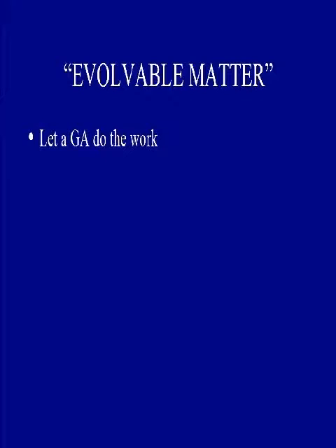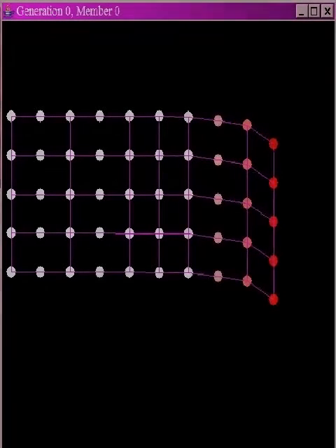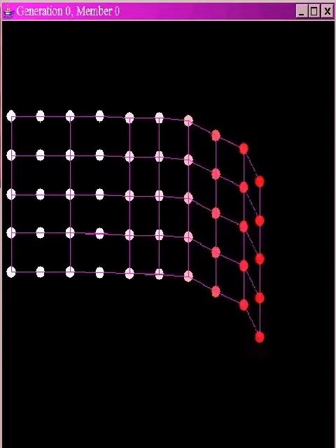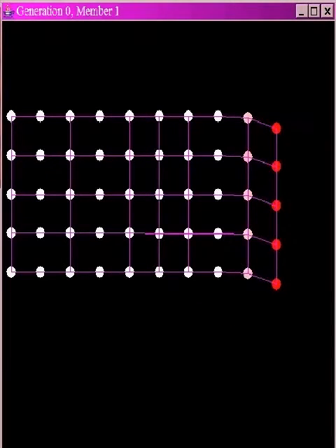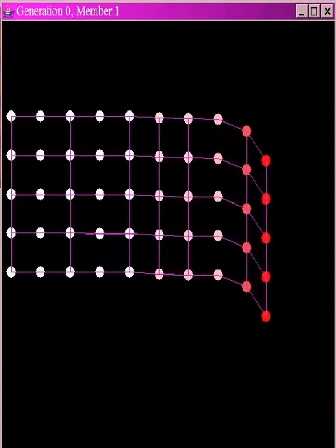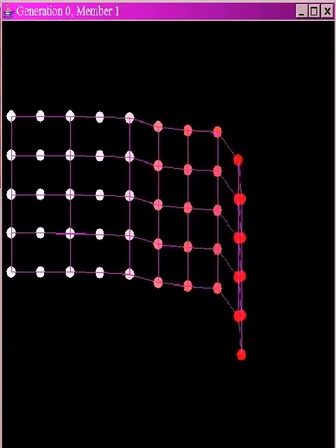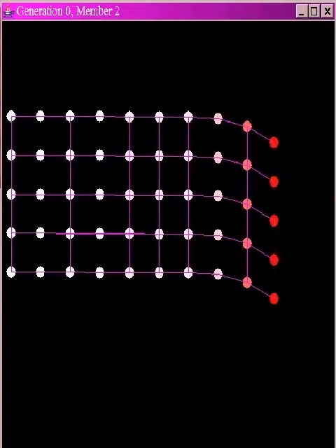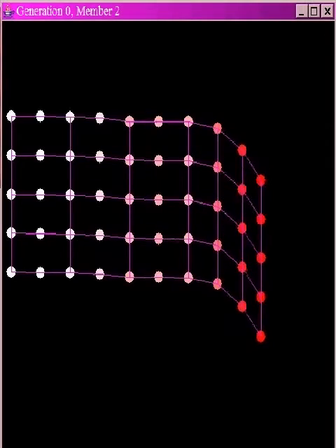In this example, a 5x10 lattice with a linear deformation is desired. Rather than conducting an analytical study of the physics of this complex system, one takes a genetic approach by creating a population of random materials, or individuals, 30 individuals in this case. Each individual is characterized by the rigidity values of each connecting rod. As each individual is subjected to an external force on its right edge, the resulting behavior is simulated and analyzed.